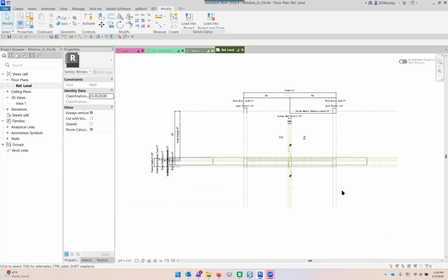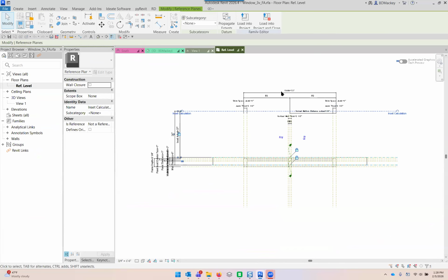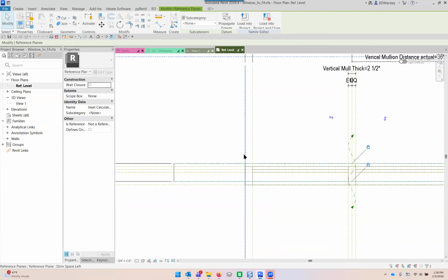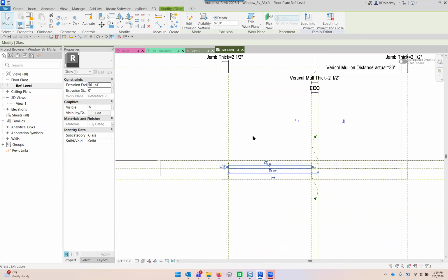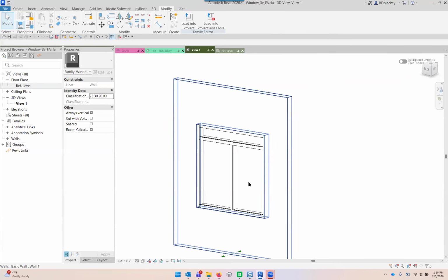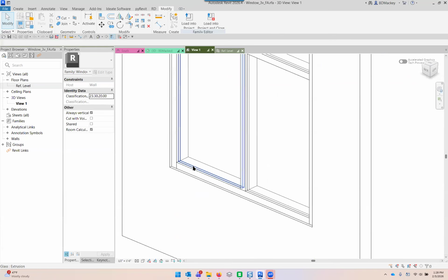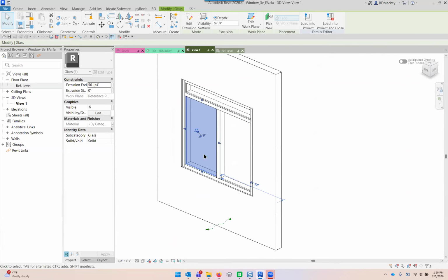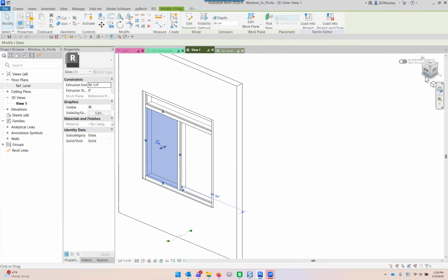There are pre-built rules for that. When you place a legend component in plan, this is the front side, right? I have the glazing on the front side, but when I go to a 3D view, I'm looking at what in Revit is the front side, but the view cube says back side. So in my mind, the back and front words are incorrect. The left and right are correct, but front and back are wrong.